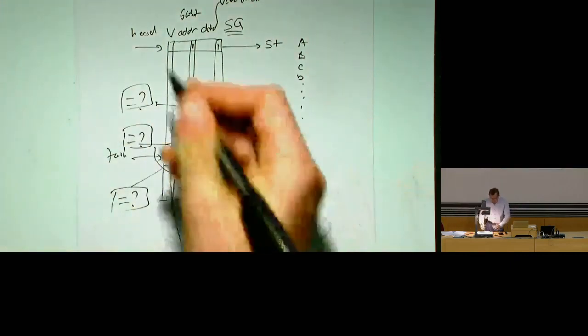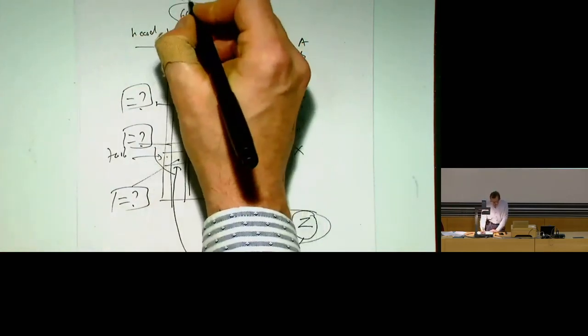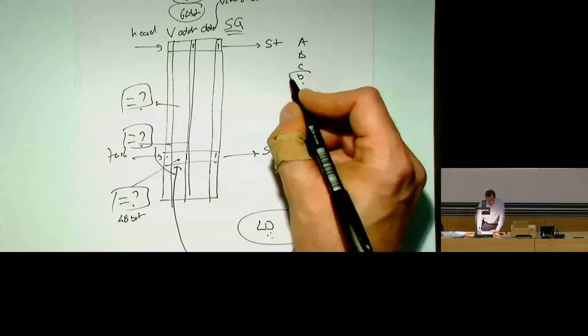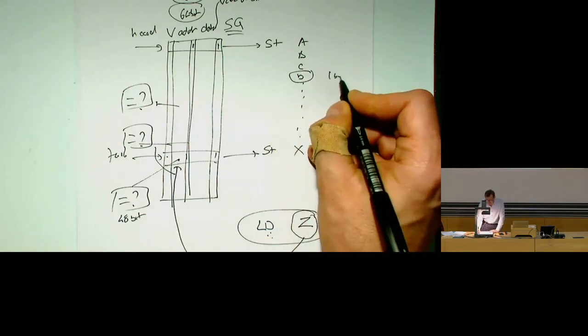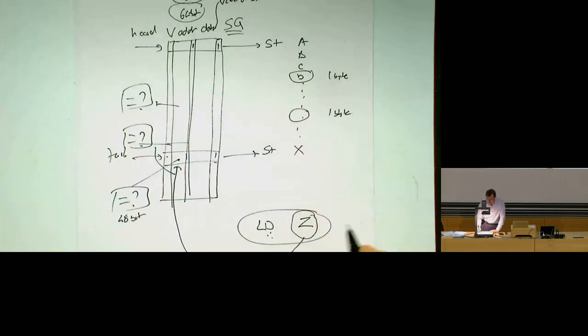I exaggerate a bit because normal machines don't use the entire 64-bit address space. Let's assume that it's 48 bits. That's more realistic. So it's a 48-bit comparator of address. And you do this. But is that enough? That's not enough, right? I've given you an example earlier where one store is writing to 1 byte over here, another store is writing to another byte, and this load is reading these 2 bytes.